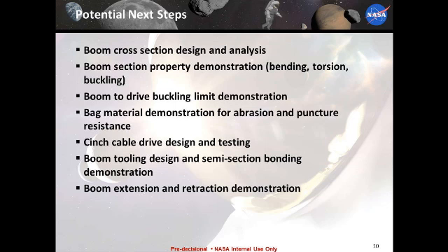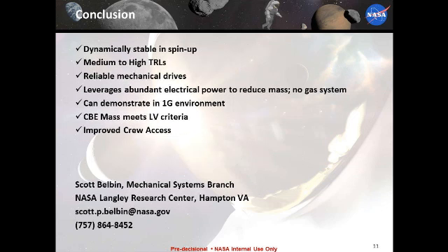That's going to be a hot spot in bending. So we'd have to have some amount of compliant members at that point, either by having thicker wall sections in the booms or having some compliant members in the drive. Bag material demonstrations and puncture resistant tests, et cetera. Going a little fast here.